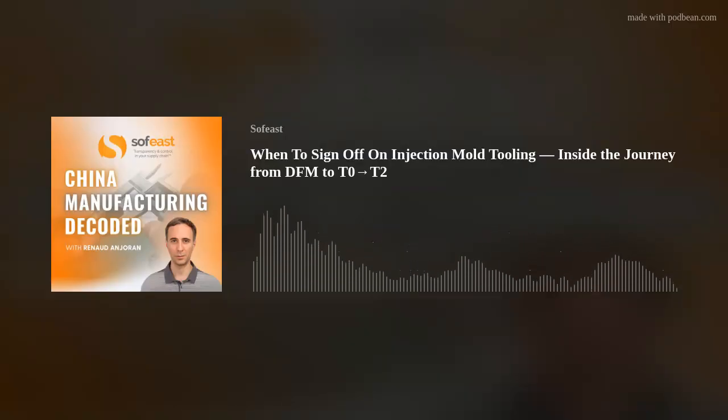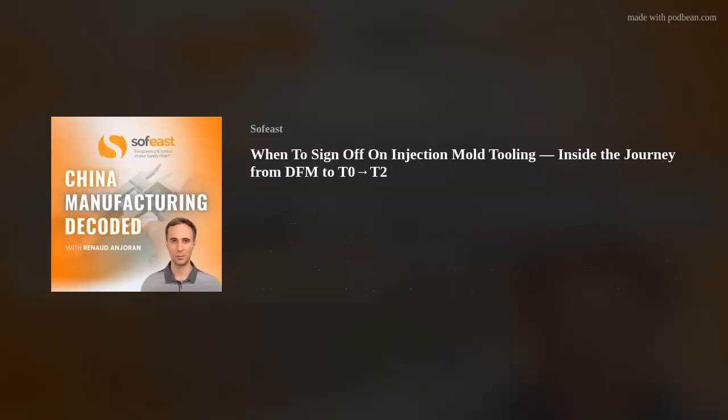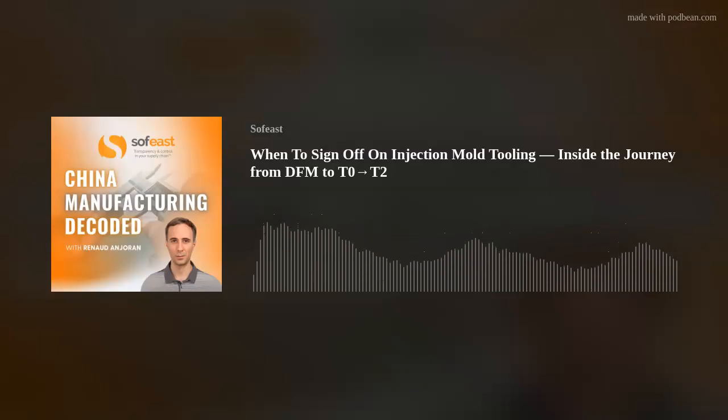We've got some videos of this we can put on the website. As the copper or brass part comes down onto the steel itself, electric current goes between them and makes a spark. That spark is eroding the steel into the shape of the insert itself.